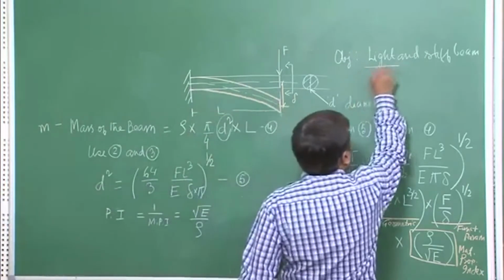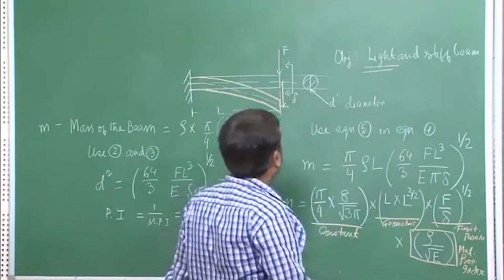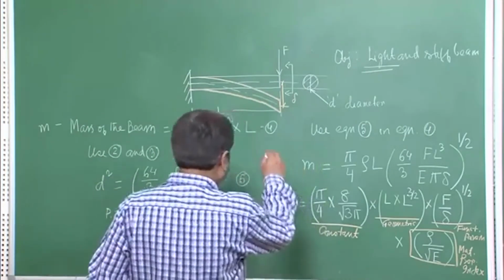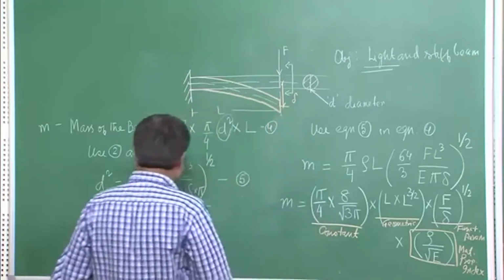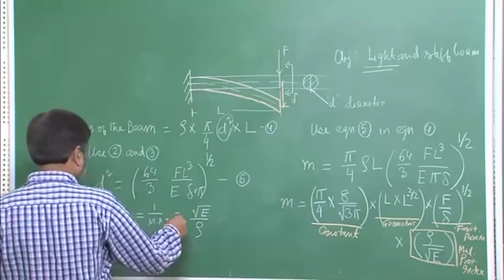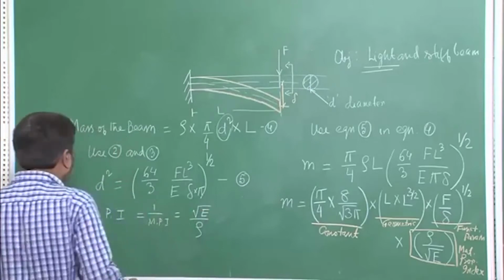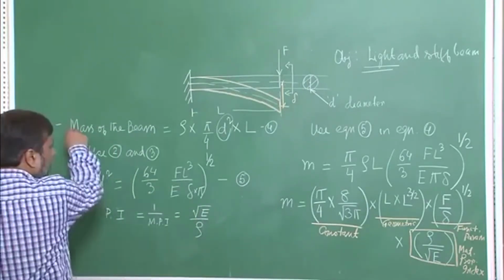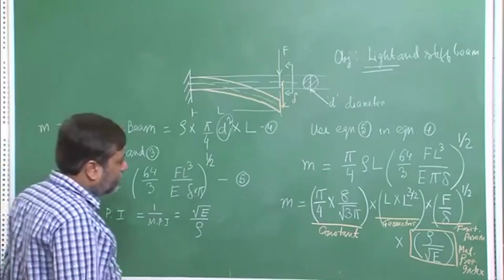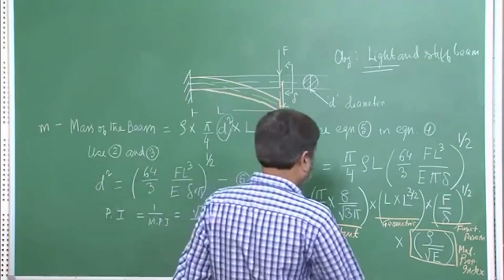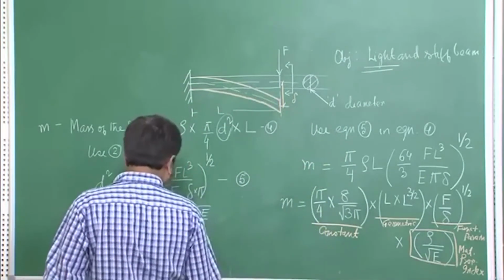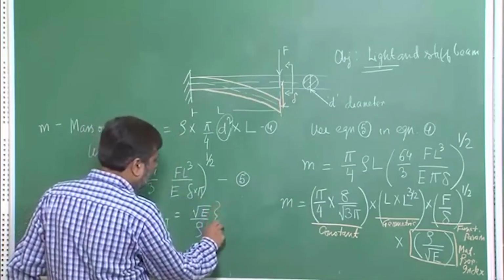Our objective is to get a light beam as well as stiff, and the stiffness is such that the deflection delta is satisfied. That is why the E term is already here. Now, from all the solutions, if I want the minimum mass, I have to minimize rho over square root of E, and that means I have to maximize this term.